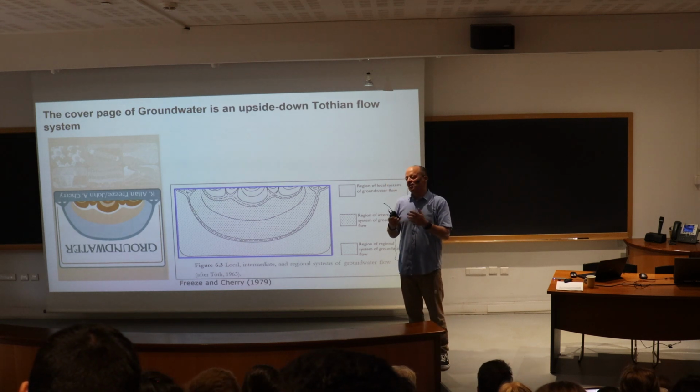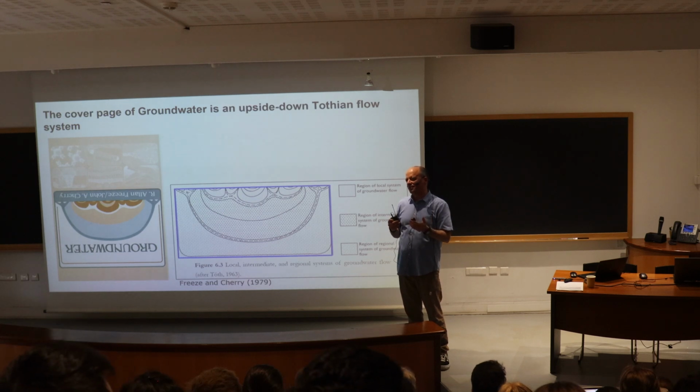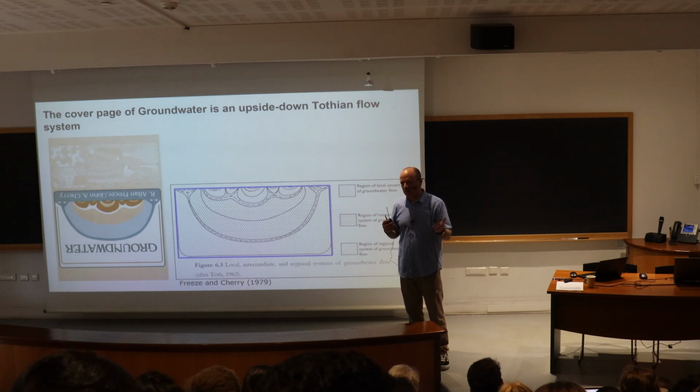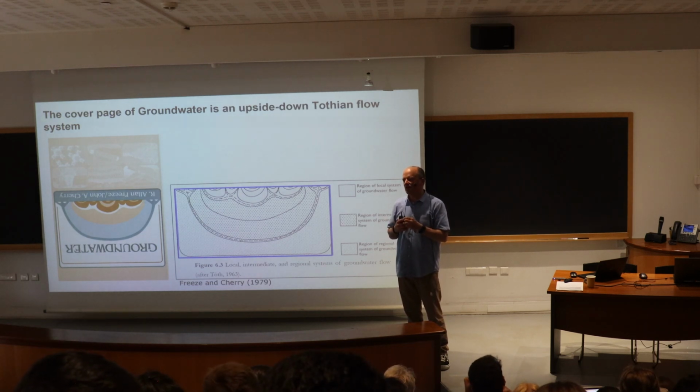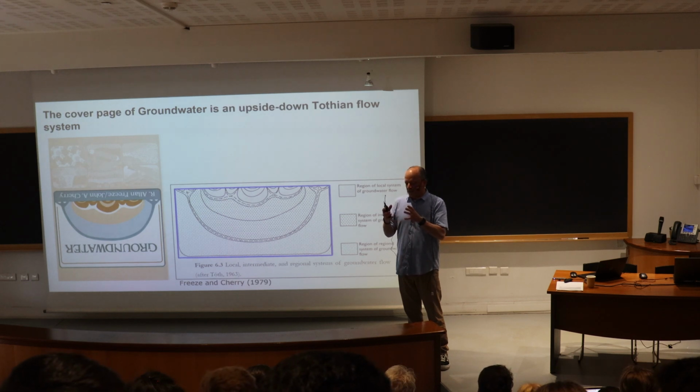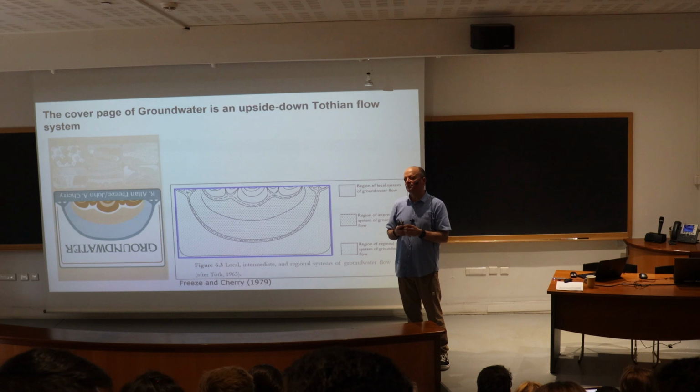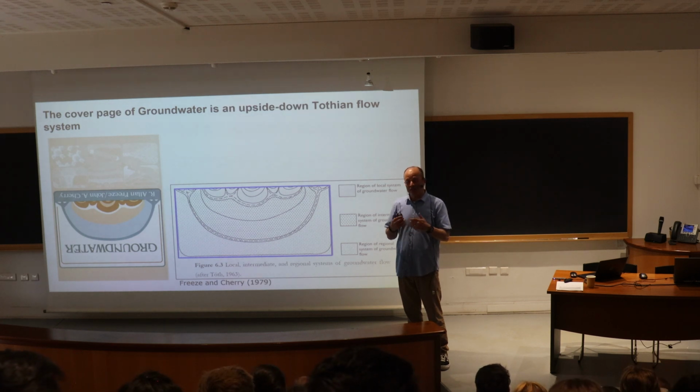But that's this concept of dynamic. People use different words: dynamic, kinematic porosity, which is the proportion of porosity that really contributes to flow. But I would say it's a concept that is real, but to measure it, to come up with values is tricky.